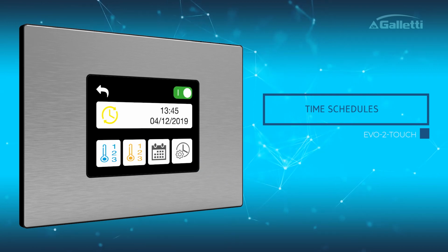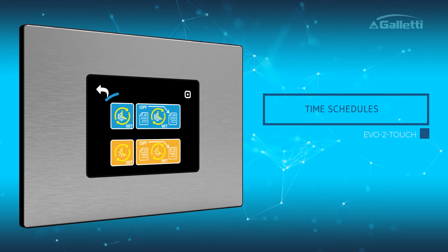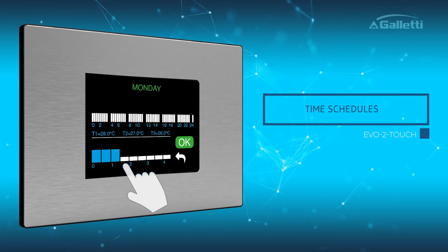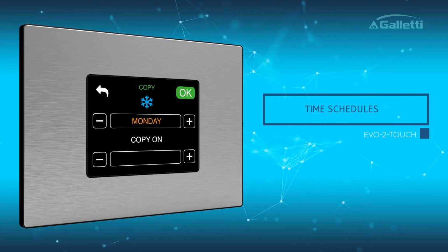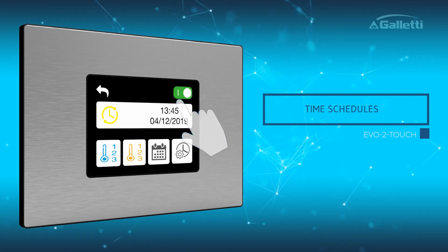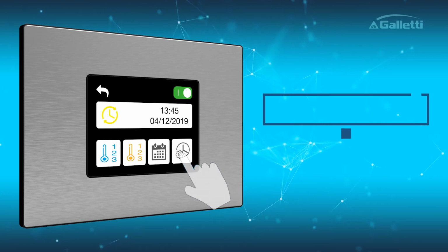Click on the calendar icon to access a screen with the Set and Copy functions. By pressing Set, it is possible to set the time slots for every day of the week, hour by hour. The Copy function allows you to copy the settings of one day to any other day. On the home page of the time slots menu, it is also possible to change the time by clicking on the clock icon.